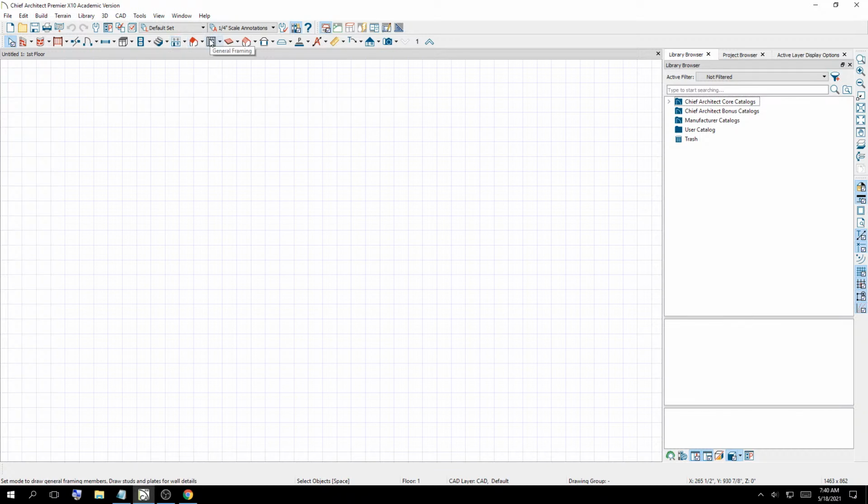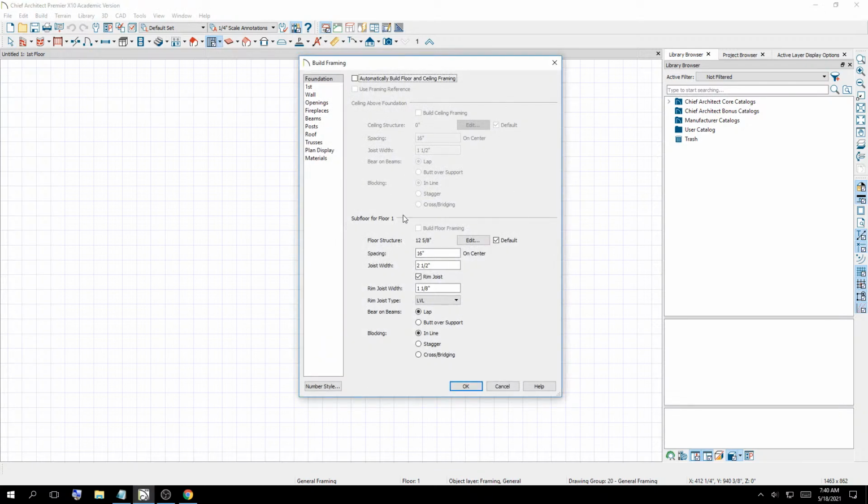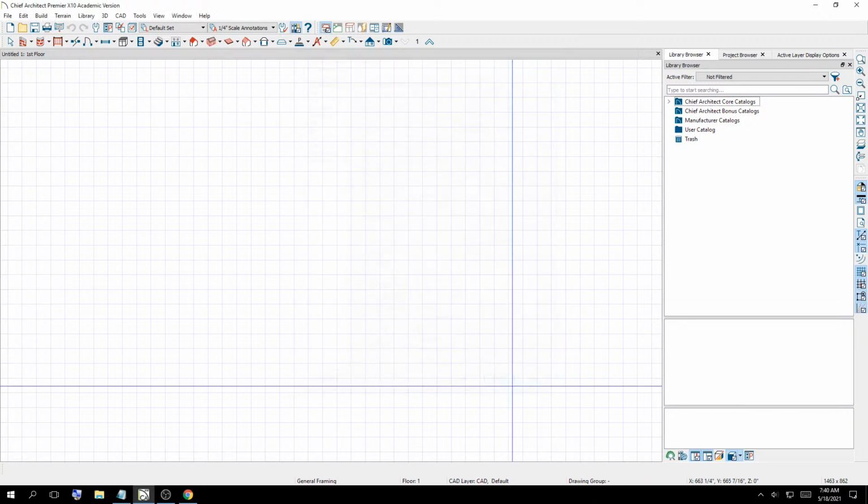auto generation of framing. What we're going to be doing today is going to assume that there is a frame there. However, without going through this specific menu and generating the framing tools and the frame itself, there won't be one to show in terms of a drawing. So if you were to do some construction work and you would need to have actually a plan for your frame beyond the assumed 16-inch on center stick frame method, you would then want to build that.